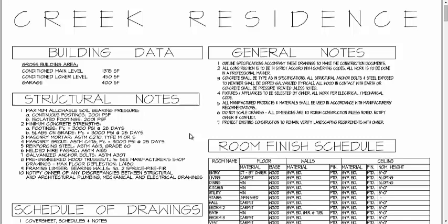Sometimes you guys hear that called IRC. And the IRC is going to tell the inspector what type of materials are okay, what type of spacing for your studs are okay, what kind of connectors, nails, screws, all that kind of stuff. So they're going to go through and verify to make sure it was built according to that code.